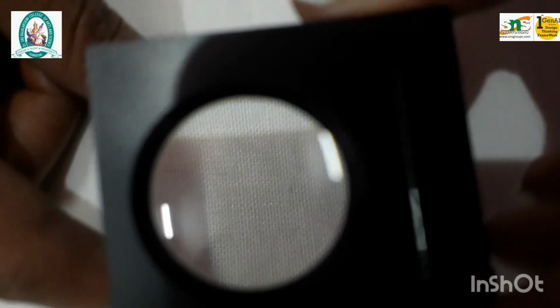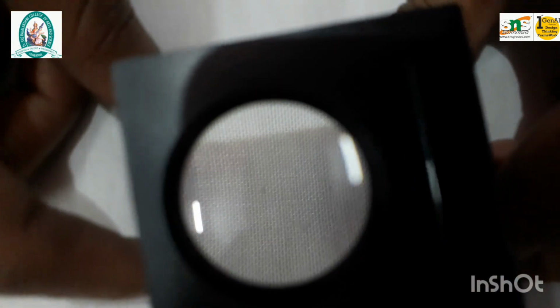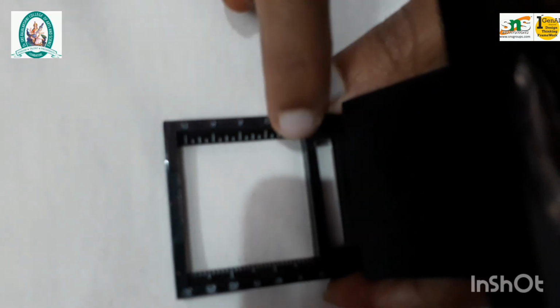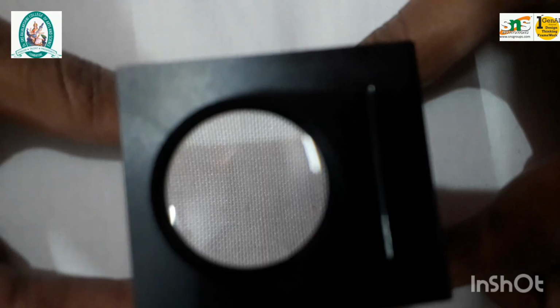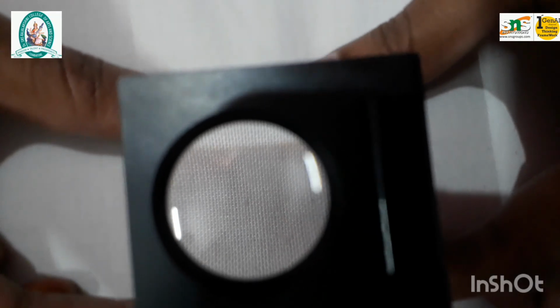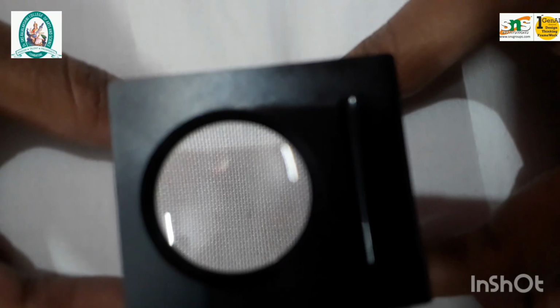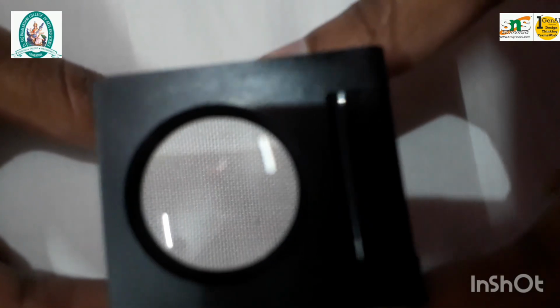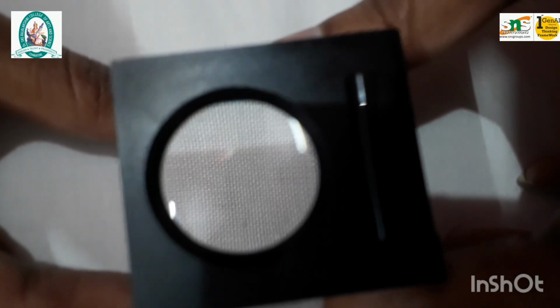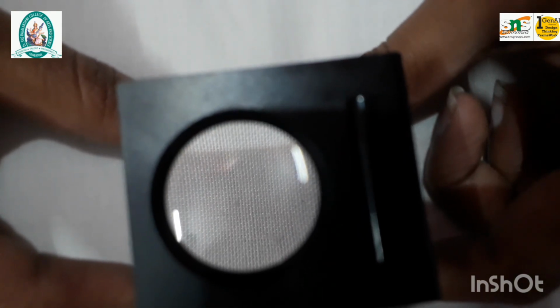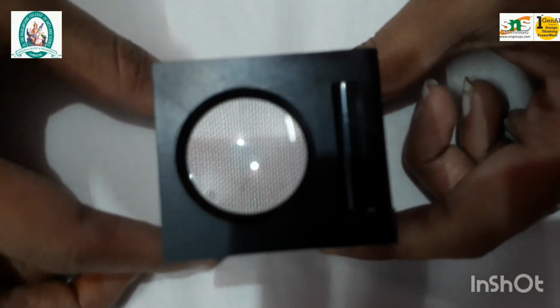Using this pick glass, we can see how the yarns have been interlaced. In this pick glass, there is 1 inch of space, so we can see how the yarns were interlaced and how tightly they were woven. The interlacement has been clearly viewed using this pick glass. Like this, we can find out this is one up and one down. So the plain weave pattern is one up and one down.